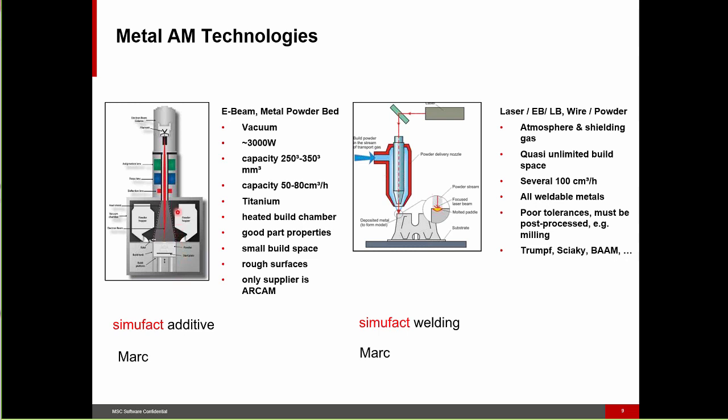The chamber itself is usually evacuated, though perhaps some argon is put in as well to prevent oxidation. We generally have a thicker powder and a thicker powder layer, so we tend to have rougher surfaces, and we might need additional follow-on surface finishing to be done.